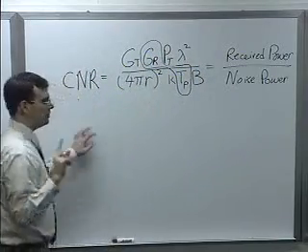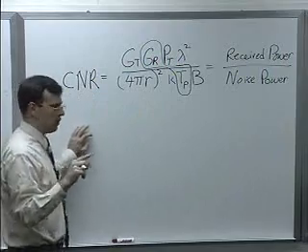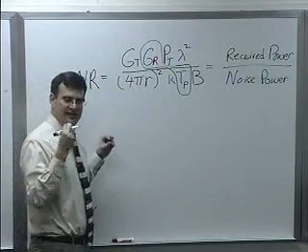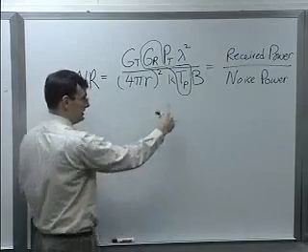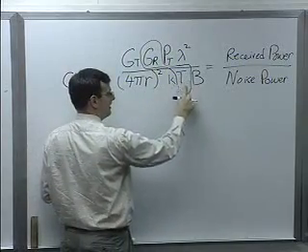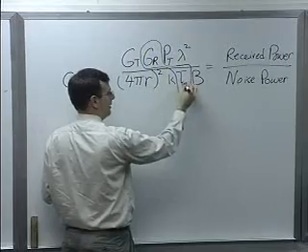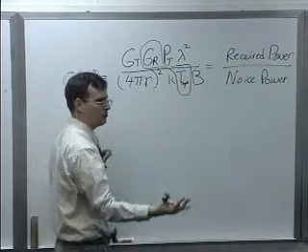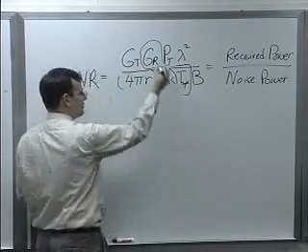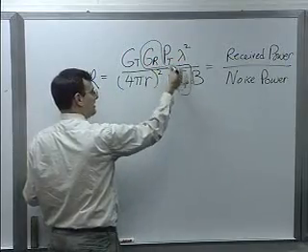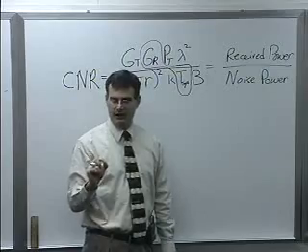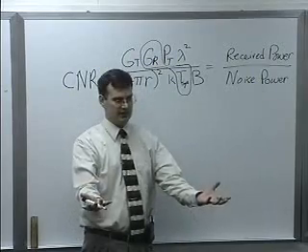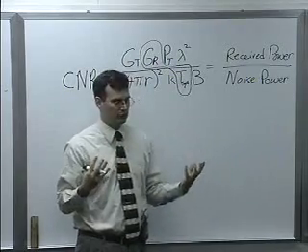And so what we're going to do today is, first of all, talk about once the noise gets into your system, we're going to add some noise to it. And so this T sub P is actually going to become a system temperature based on all the possible sources of noise. And this G_R over T_S ratio is actually a really good metric of how good your receiver is, because all the other stuff you really don't have control over in a link.